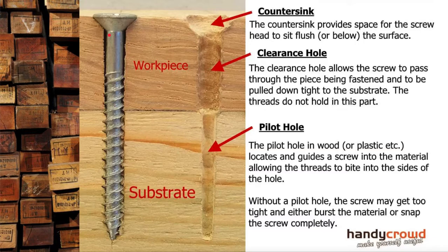Okay, so definitely, no matter what you do, always pilot hole and always countersink hole. The clearance hole is an extra bit of work, but definitely a benefit to you if you're working with a hardwood on the surface being screwed into a softer timber.